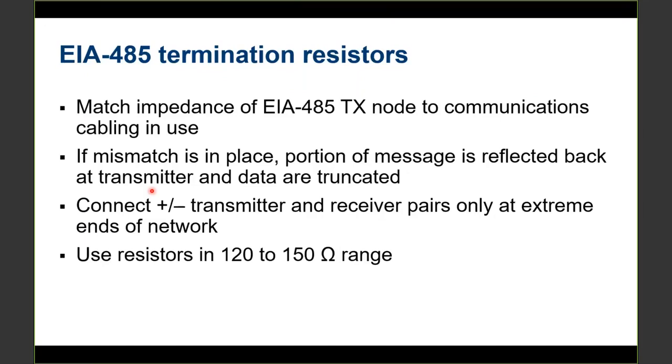And also, if you did have to add a termination resistor to prevent these reflections, if you're having issues, then basically you would connect your plus and your minus networks together with this resistor.